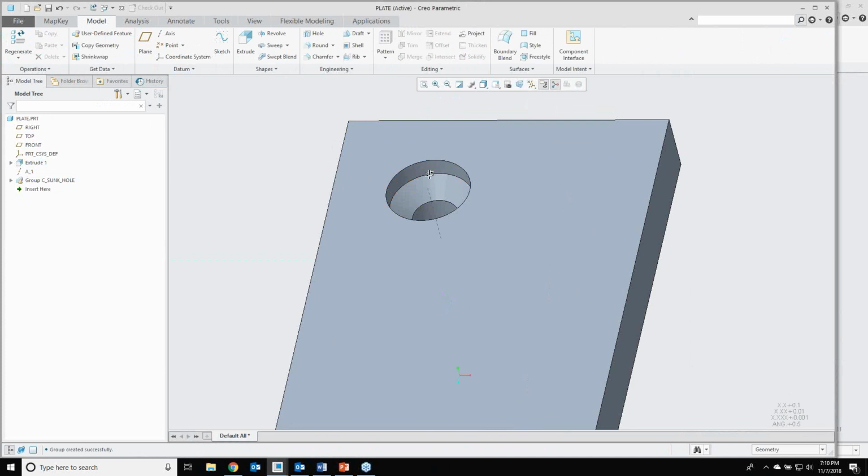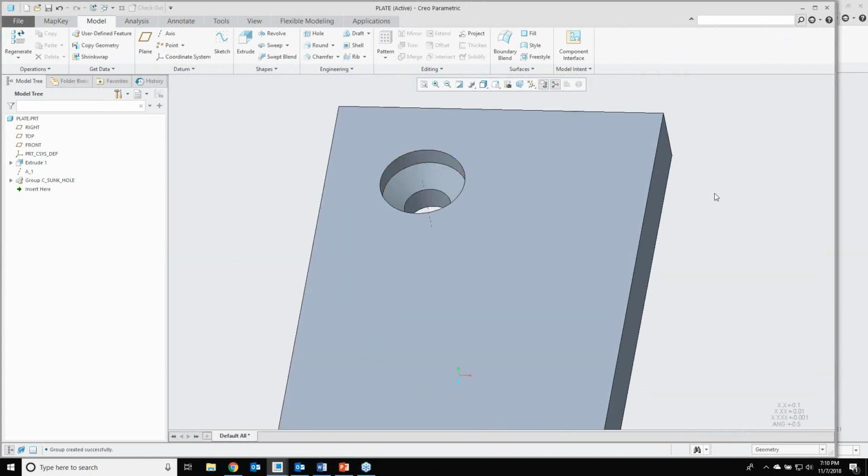So that's a fairly simple example, but it's really powerful. You can really use that. You can even go back to old designs that you've done, and if you need to reuse that again, just quickly grab them, add them to a library, or just put them in your working directory when you create your UDF, and then you can apply it in your new design. So it's not driven from anything else. If you go back and you change the old design, this one's going to stay like that.